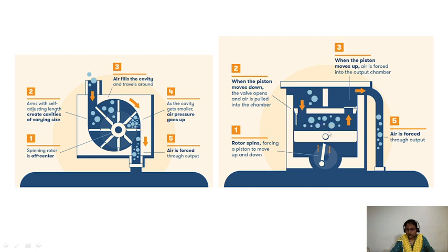Now when the piston moves to the top dead center, or reaches the extreme top, this air will be fully compressed and it will exert pressure on the outlet valve, which is again a one-way valve which will open only towards the outside direction. Here the inlet valve, opening only in the inward direction, will be kept closed by the compressed air, whereas the compressed air will put force on this outlet valve or exhaust valve and it will be forced open, and this compressed gas will be released and forced out of the compressor and will be stored in a storage tank, which can be later used for any of the industrial applications.